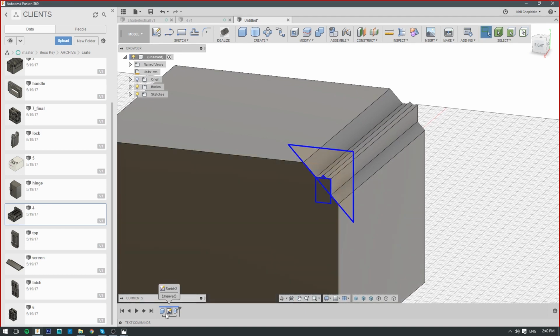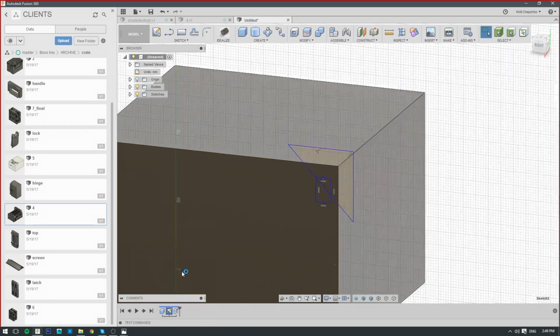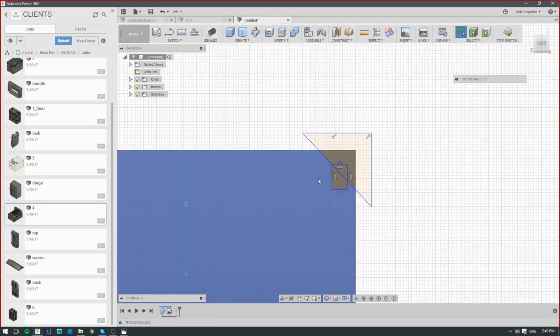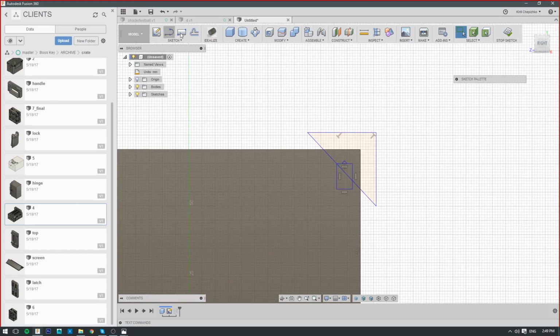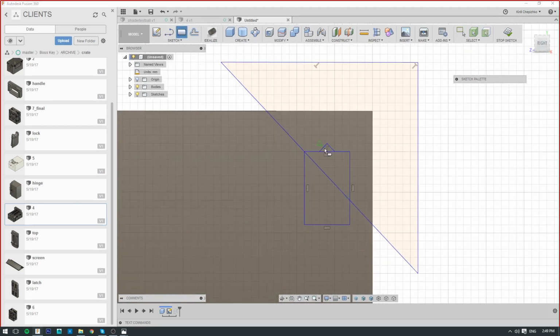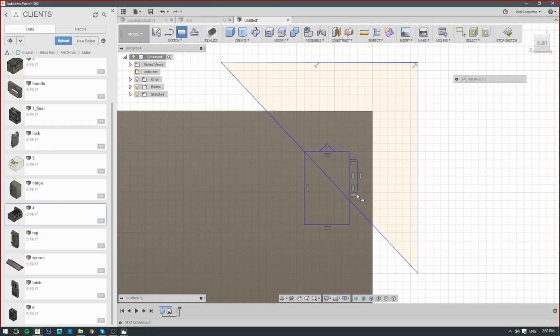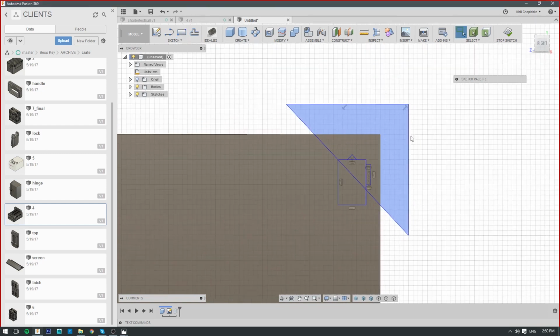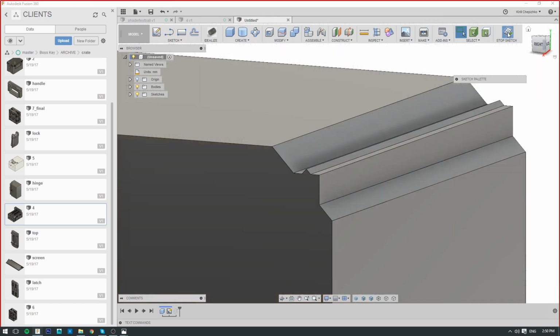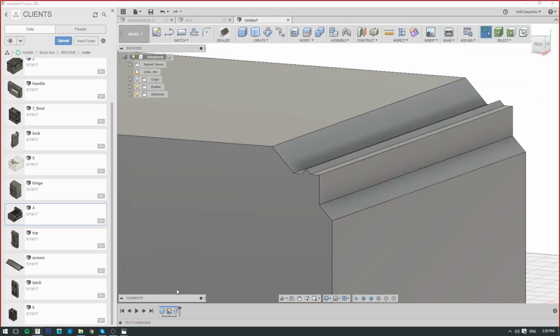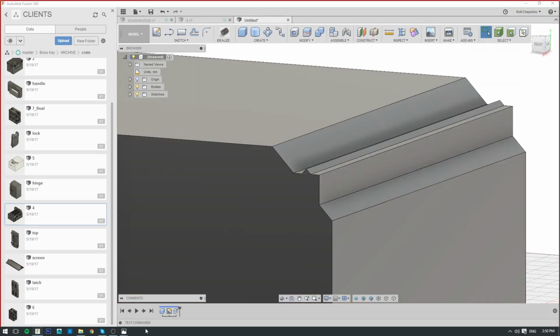For that, you need to go edit the sketch in the timeline. If you're watching this and we haven't explained the timeline yet, we will at some point. But basically, you go back and let's say you wanted to alter your sketch, and then stop sketch. It doesn't always compute, but the sketch will be there.